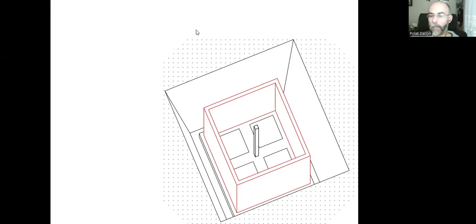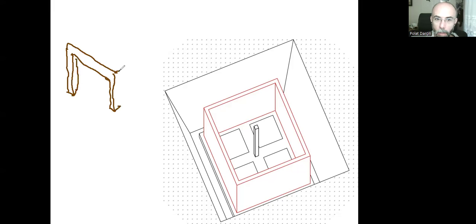Here, if we create a shear wall, the whole reinforced concrete shear wall will be carrying all the loads. It's something like a long, big column. So we don't need separate columns. We don't need to combine them with beams because it's just one load-bearing surface. In the frame system, I create one column and I connect it with the other column with a reinforced concrete beam, like this here.